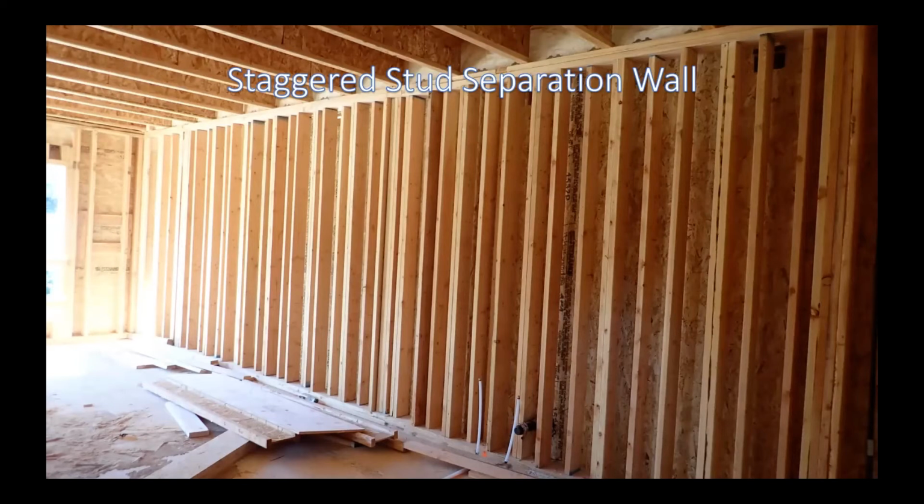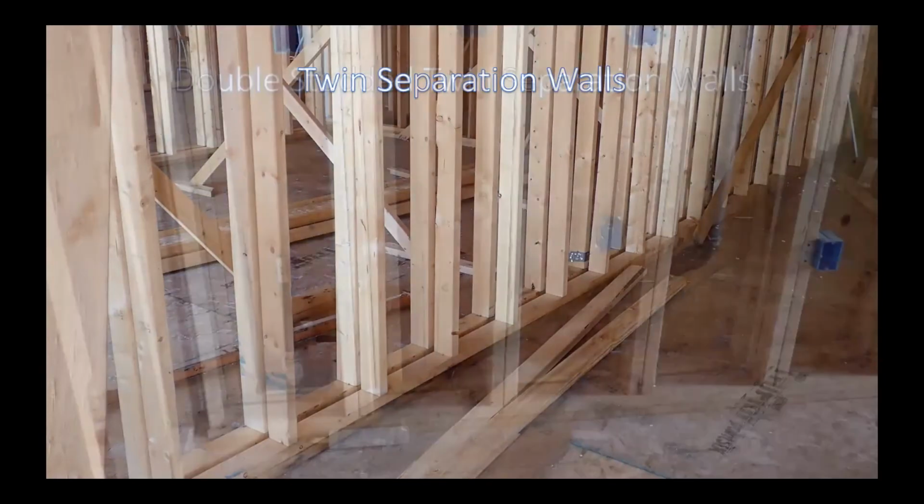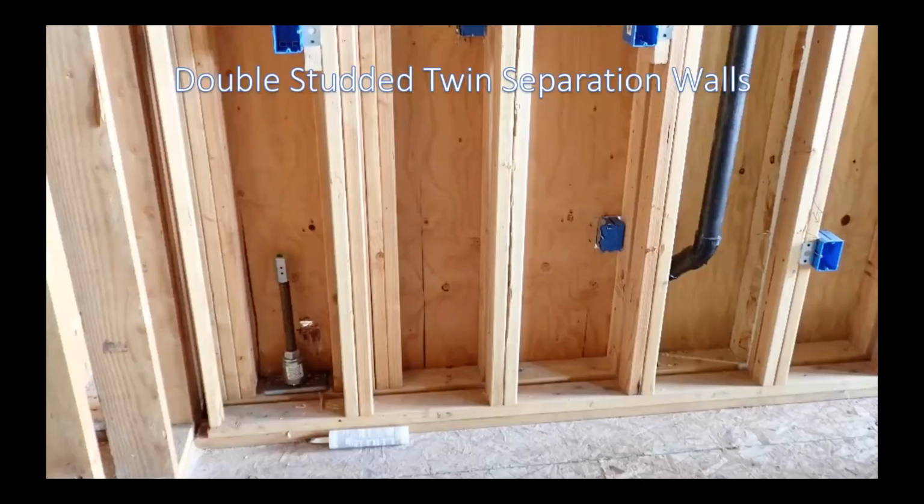We see staggered studs with single top and bottom plates, wider top and bottom plates to create that separation between the occupancies. But probably more commonly, we see twin separation walls, like we see over here, to separate all the different compartments and apartments, and double studded twin separation walls as well. They use them more.